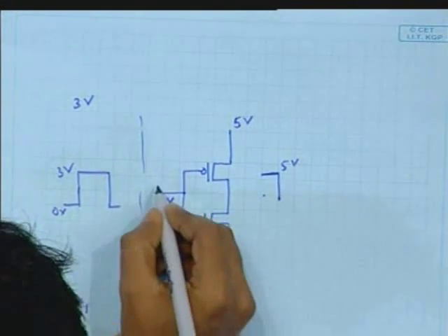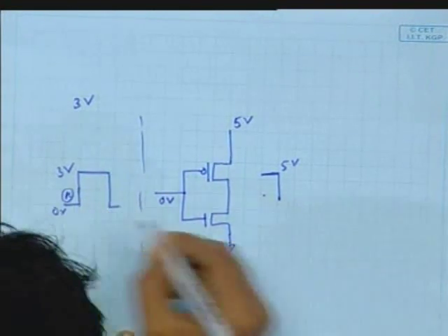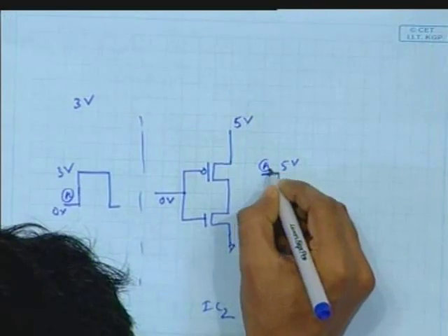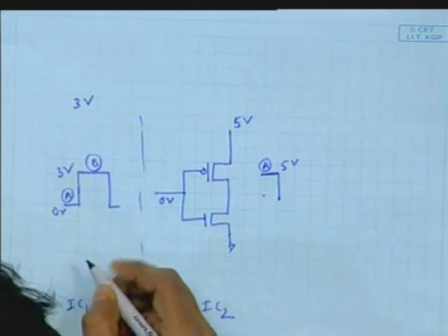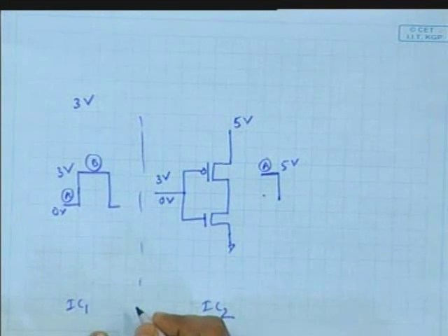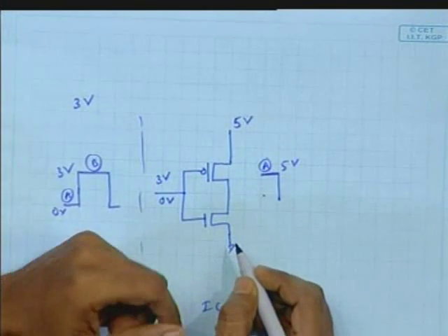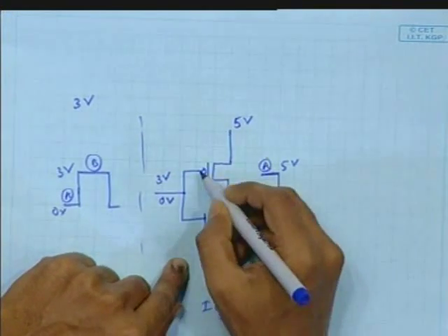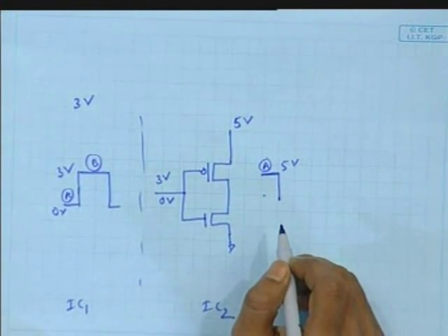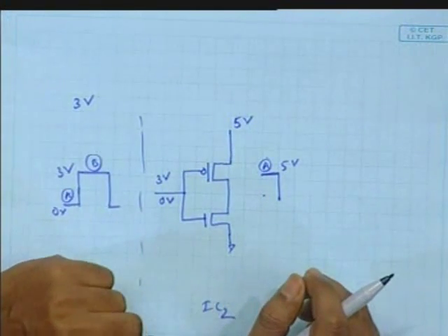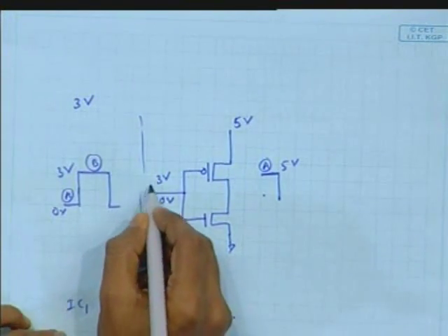Now if this signal is here at this point, this is considered point A. During A we are getting A here, right? And now we consider this is B, 3 volt. So 3 volt has come here. At that time, NMOS should be on, right? But at that time you see this is also on, so it will act as a divider, right? Because PMOS is not turning off completely, you have to turn off that one. So some circuit we have to put at the input stage.